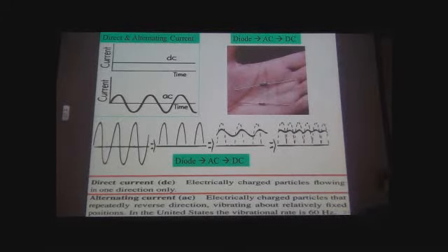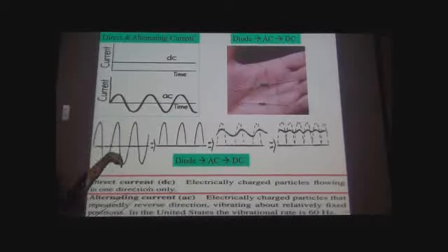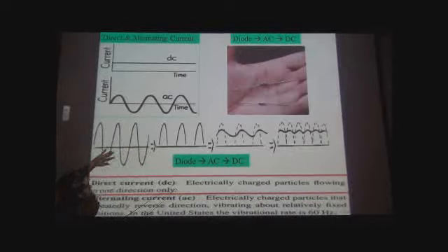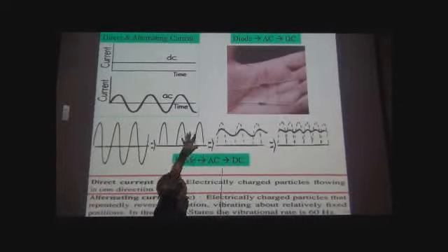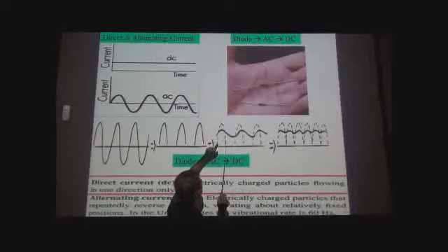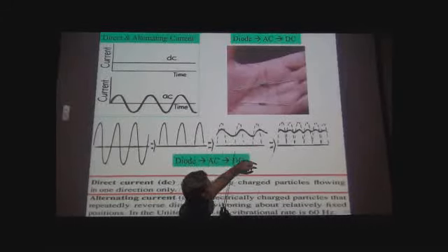So the diode ensures that the traffic is traveling in one direction here, and over here you can reverse the diode and it travels in the opposite direction, as opposed to a two-way road where the electrons can travel in both directions. What the diode does to this alternating current, remember that this is a positive current, that's a negative current, positive, negative, so you've got the sinusoidal variation in the current. The diode clips, it removes the bottom so that now you only have the positive pulses. You can smooth these pulses so that instead of getting the dashed pulses, you now get this kind of wavy motion, and you can do things to make it even better.